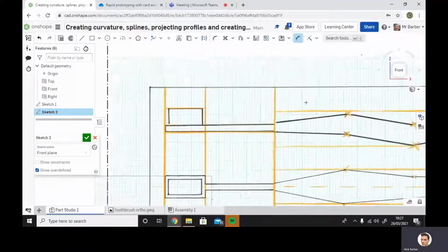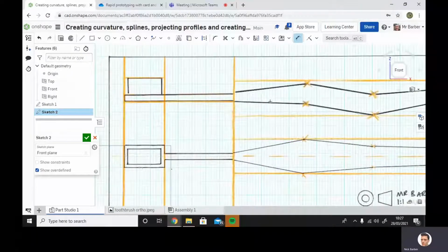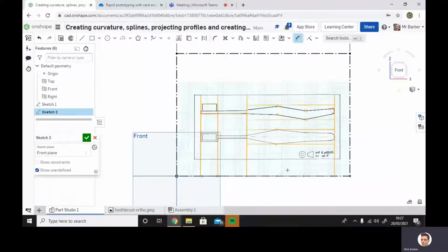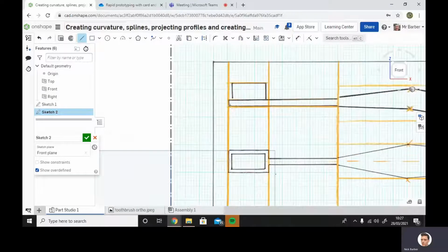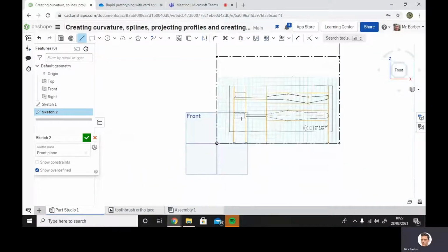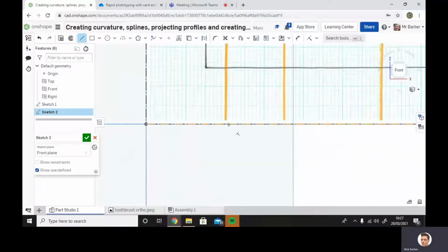Now what I'm going to do is draw this bottom profile and the top profile, and I'm going to project that plan view up to these different profiles as well. Okay, so again, combination of line tool, we'll drop the first one. Now what we should do is, I've got those points that I dropped in there. If I float above that or float on it,